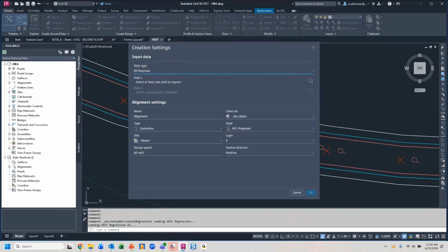For example, a left and a right-of-way line. Maybe the crew didn't shoot the center line, right? But they made and shot the points for the right-of-ways. What you could do is you could utilize those two sets of points, okay? And then the software would literally create a center line based on the locations on each side. That part to me is pretty impressive.